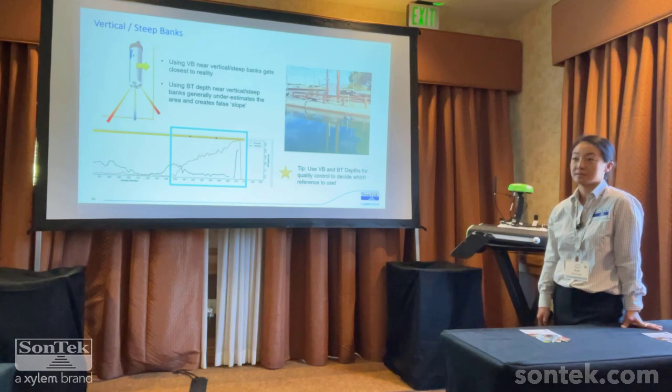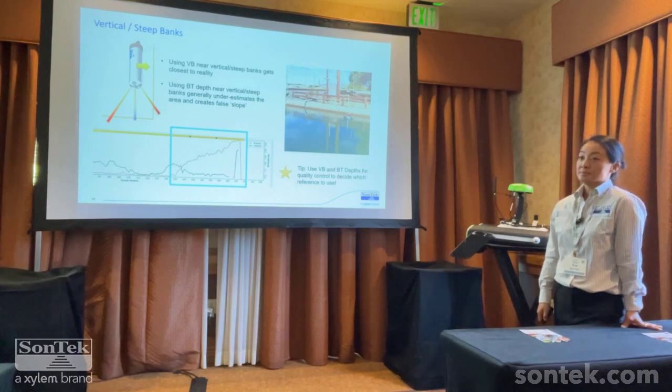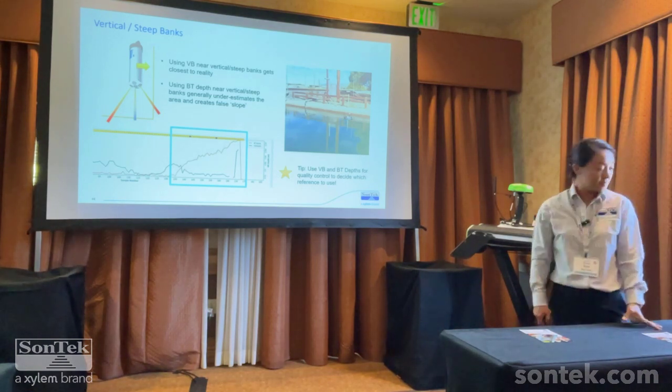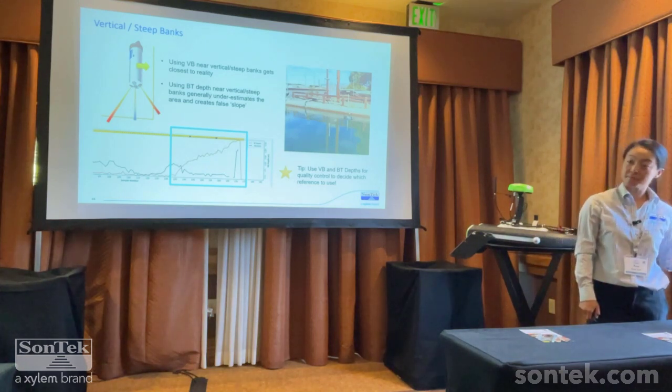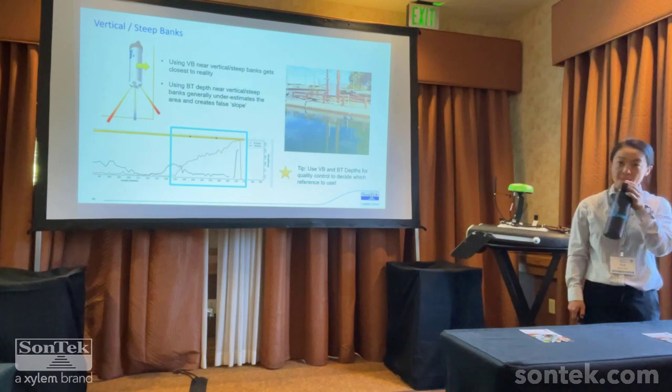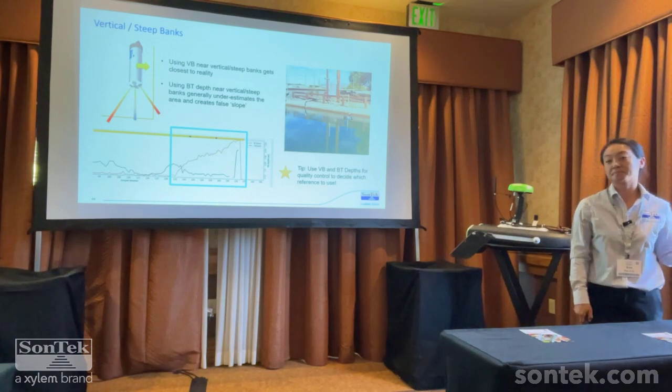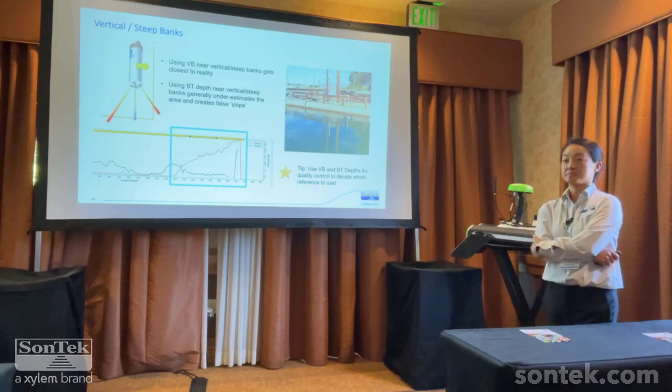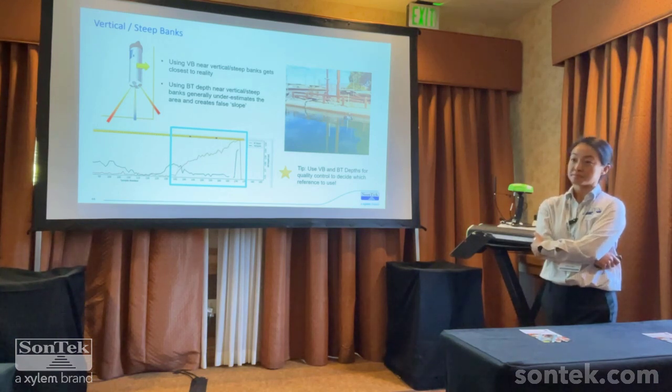That's right. Okay. And it might be worth mentioning that using the bottom track depth or not using the bottom track depth has nothing to do with your velocity measurement. Right. It's only for depth. Right. Even though it's bottom tracking for water velocity and then bottom tracking depth. If you choose vertical beam for depth, it has no impact on your measurement if you're using bottom track.